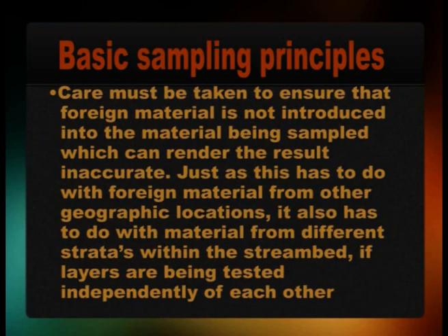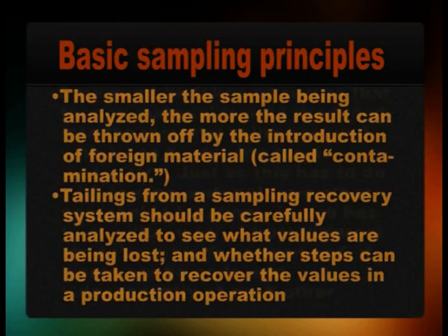Care must be taken to ensure that foreign material is not introduced into the material being sampled, which can render the results inaccurate. This has to do with foreign materials from other geographical locations, and it also has to do with materials from different strata within the stream bed if layers are being tested independently of each other. The smaller the sample being analyzed, the more the results can be thrown off by the introduction of foreign material, called contamination.